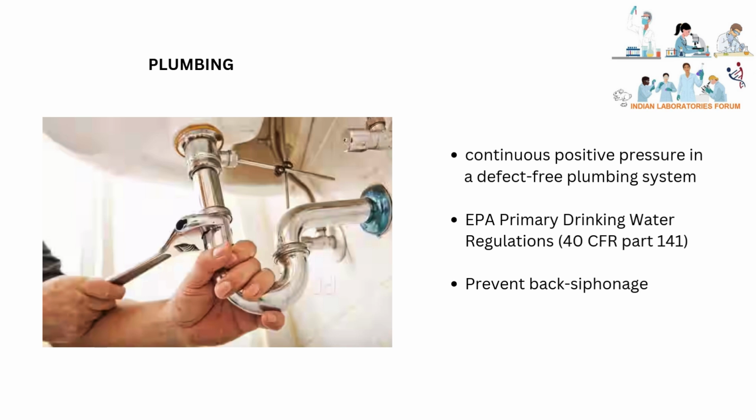Manufacturers should continuously ensure that water meets the requirements as per 40 CFR Part 141 and should test the water with a defined frequency. Drains must be sufficiently sized and, if directly connected to a sewer, must have an air brake or another mechanical device to prevent backsiphonage.